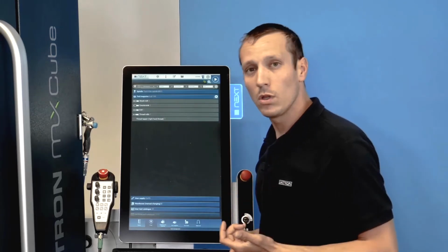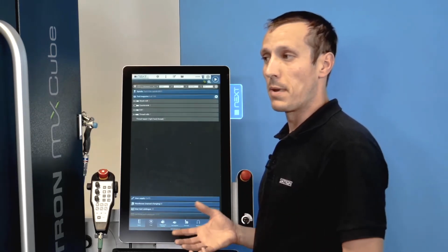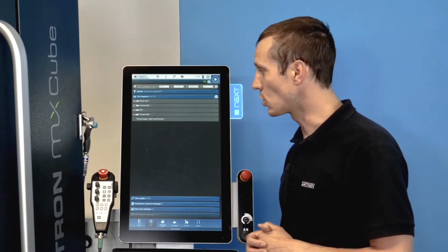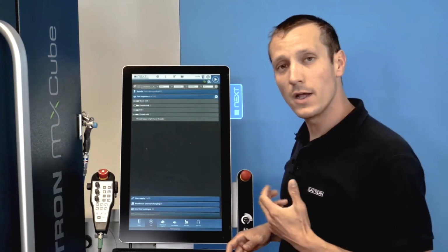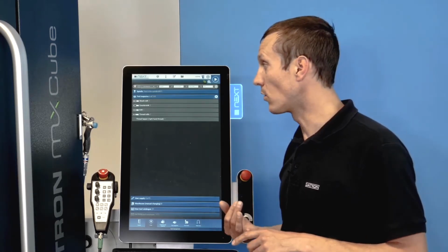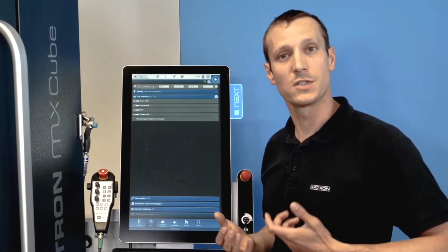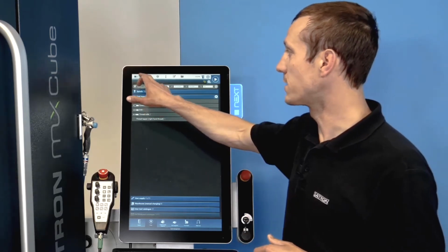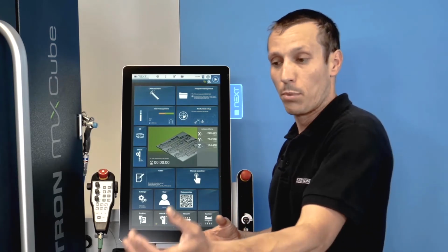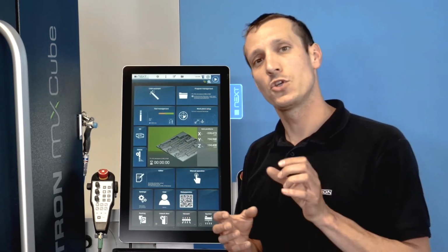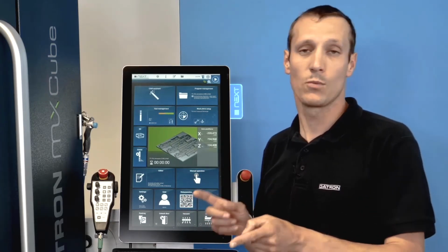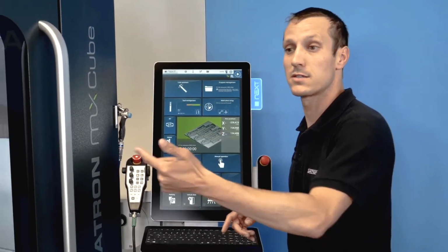We also got the tool management. So depending on which tool magazine you have in your machine, we got a tool assist here, an external tool changer. It tells you which tools are in the magazine, article number, or just the category, like is it an end mill, is it a countersink, is it a drill bit. It tells you exactly which tools are in, and if you post a program directly from a CAM system, it would check that every tool that you have programmed on your computer is in the machine and will tell you you need to set this or another tool up.